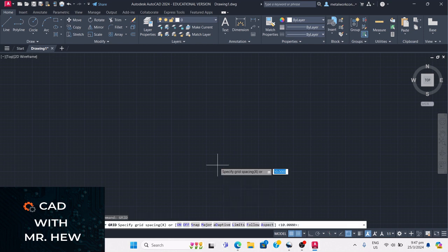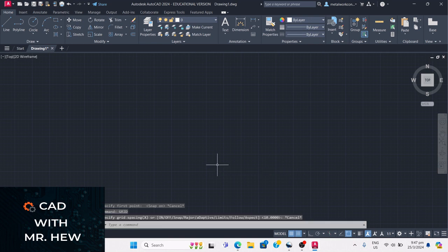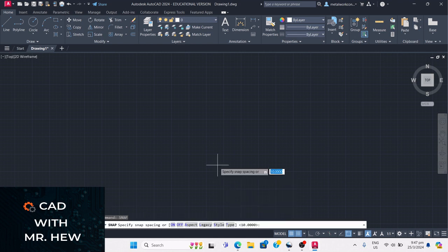The last spacing that I had on my current AutoCAD software is 10 millimeters, right? So if I set the snap, if I type in snap, the cursor will snap onto those spaces. See this in my computer program, I have 10. I could have changed it to 5, right?